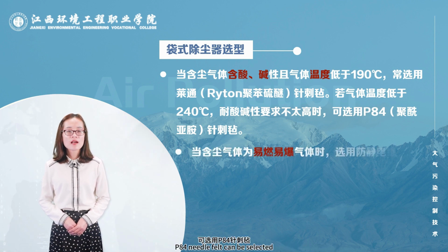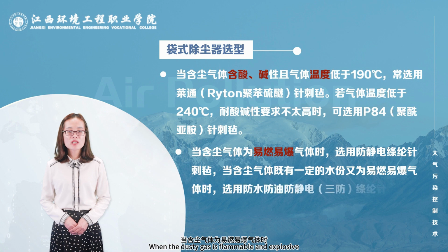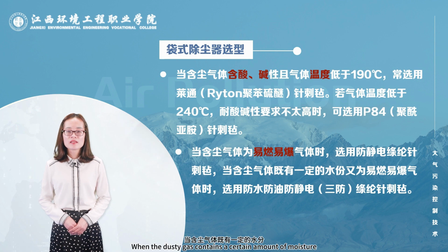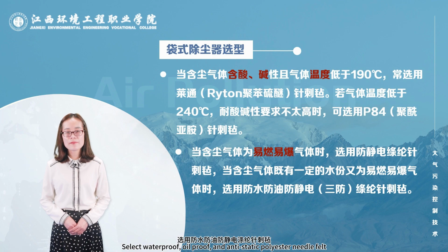P84 needle felt can be selected. When the dusty gas is flammable and explosive, choose anti-static polyester needle felt. When the dusty gas contains a certain amount of moisture and is also a flammable and explosive gas, again select waterproof, oil-proof, and anti-static polyester needle felt.